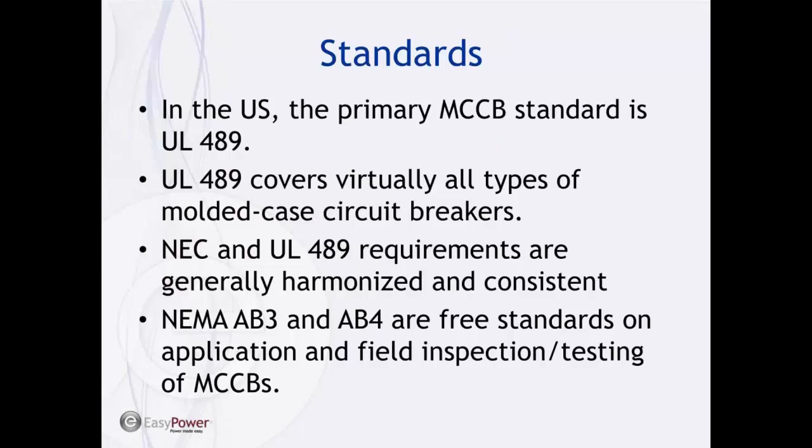If you look at a molded case breaker, you can't really tell what's going on inside, and so it becomes a little bit difficult to tell when they need to be replaced. So AB4 gives you some guidance on that, and there's another IEEE standard that we'll mention here at the end that also aids with field inspection and testing of molded case circuit breakers.